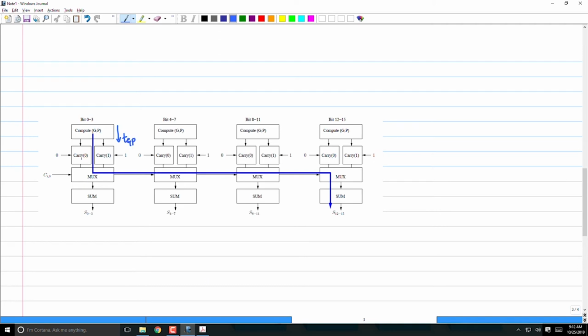Then it goes to the full adder rippling block that does evaluation of carry in equal to 0. In parallel, there is another block which does evaluation when carry in is equal to 1. Then I am going to send it through a multiplexer and the carry out will go. The sum, of course, will have its own multiplexer and all that. Okay? Right?